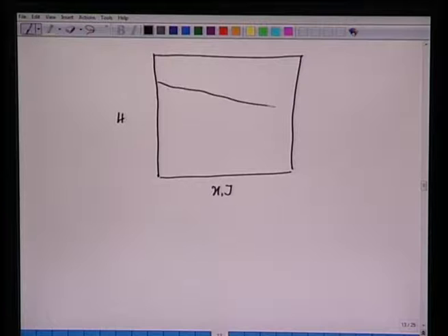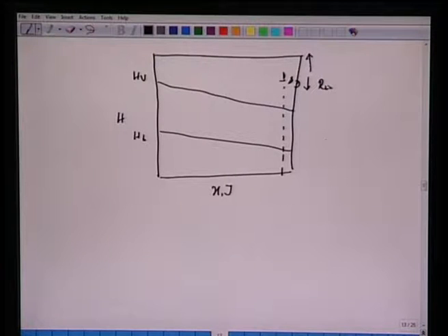So we have this HV and this HL curve. If you recall from our previous discussion, the locus of del D points will move downward if you are looking for R min, and it goes up if you are looking for infinite reflux ratios. So when this locus goes up, this point moves up, we have all vertical lines. So these are the operating lines which emanate from del D.